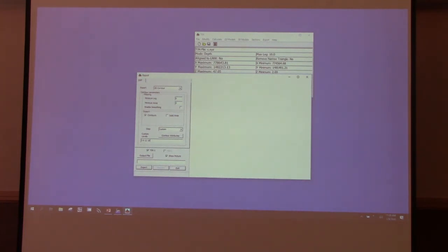But if you have data and you don't want to sit there and type a bunch of different things, you can actually make your color file match what your contours are going to be. One of your options is your color file. So if you do your spacing in your color file, the way you want your contours, it's really easy to come in here and drop this down and say, do it based on my color scheme. Everyone understand that? I like the color scheme.